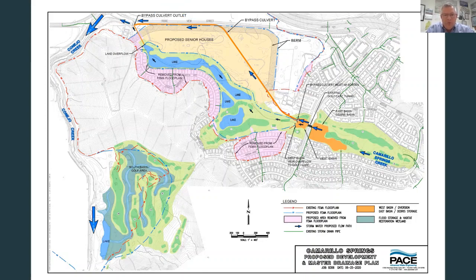The outflow from the bypass culvert is a free outflow, and it's because we collect the water at a higher elevation all the way back here where we let the water go into the bypass. This whole bypass pipeline is sloped.